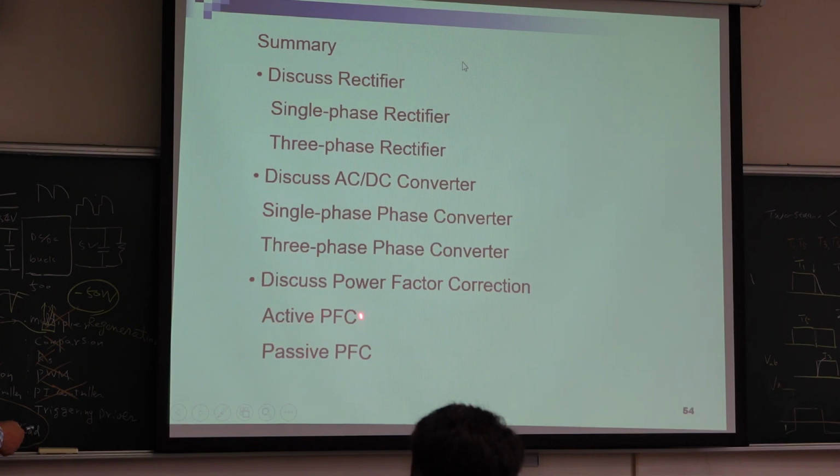The other side is active power factor correction. It is used for computers, cell phones, small power. Then we can use MOSFETs. And also we need a lot of control, a lot of sensing. So the only problem is how can you simplify the circuit and reduce your cost but get the same performance. So this is a good opportunity.